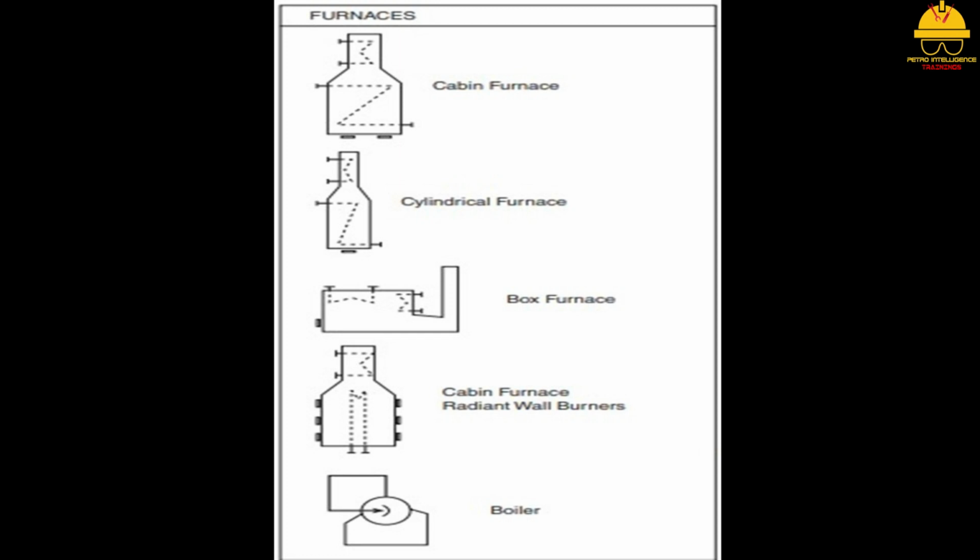A furnace is designed to heat up large volumes of feedstock for chemical processing in a reactor or distillation column. Feed enters a furnace in the cooler convection section. Heat transfer is primarily through radiant and convective processes. The hottest spot in the furnace is the firebox. Tubes in the firebox are referred to as radiant tubes.